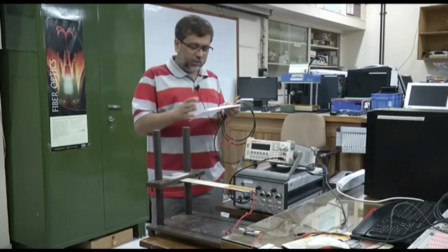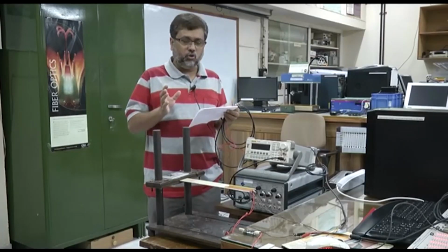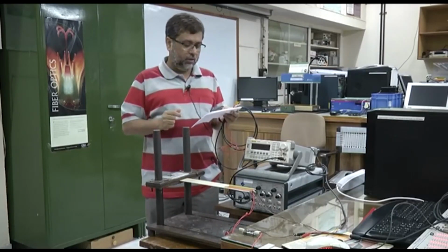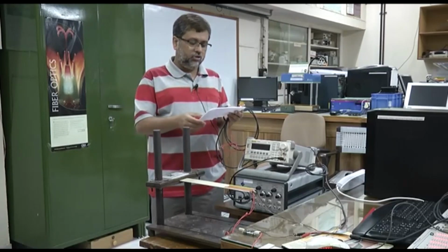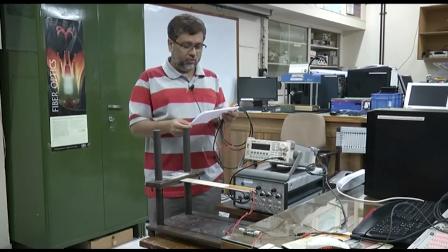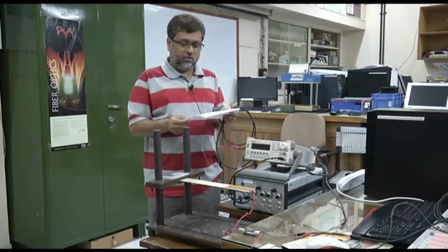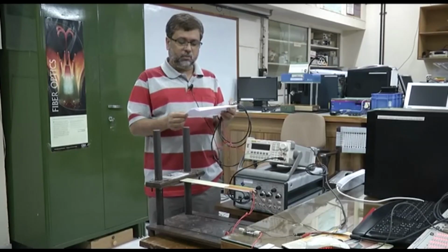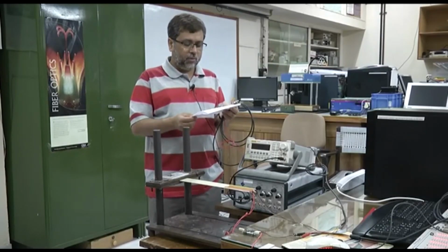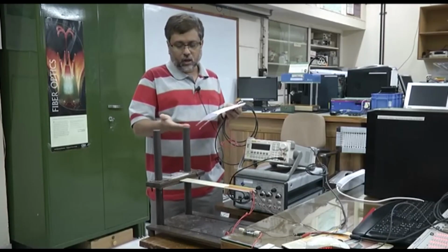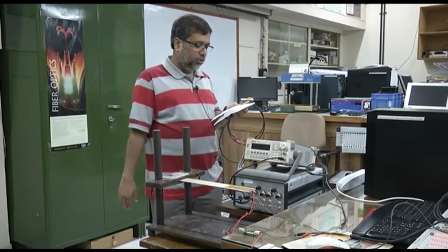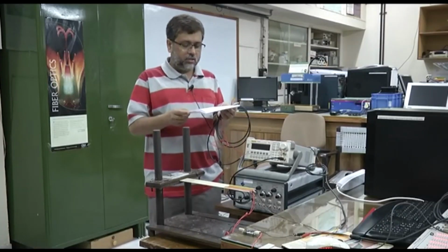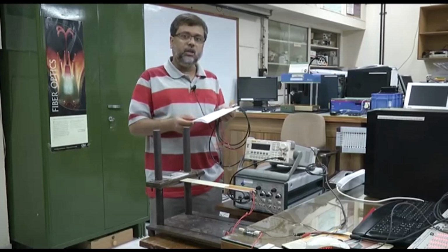The blocking force of this particular system generally varies between 28 Newton and 1 kilonewton. It depends on the width of the MFC, and the operating voltage is minus 500 to 1500 volts, and the current is about 50 milliampere, and the amplification is about 200 volts per volt. The maximum operating frequency up to which I can generate vibration in this system is about 10 kilohertz. However, as a sensor it can sense much higher excitation, close to about 3 megahertz.